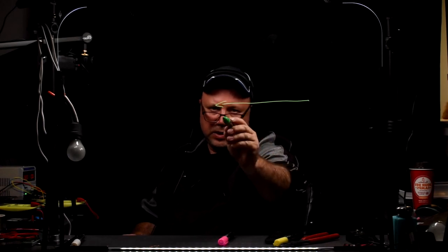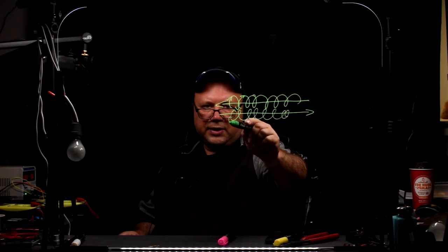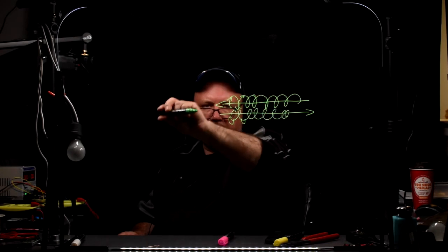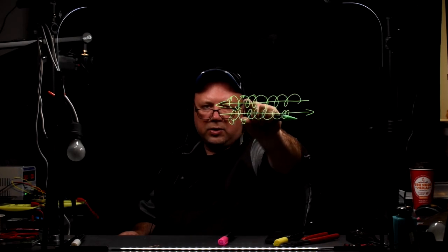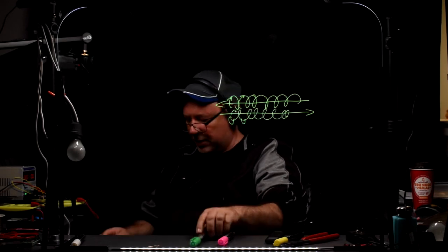Well, one of the wires is conducting current one way. The other wire is conducting the current the other way. This one here causes the electromagnetic field to have this direction. The other one is just the opposite. It's causing it that way. So the magnetic field in the supply wire and the magnetic field on the return wire are of the same strength, close to each other. They just cancel each other.